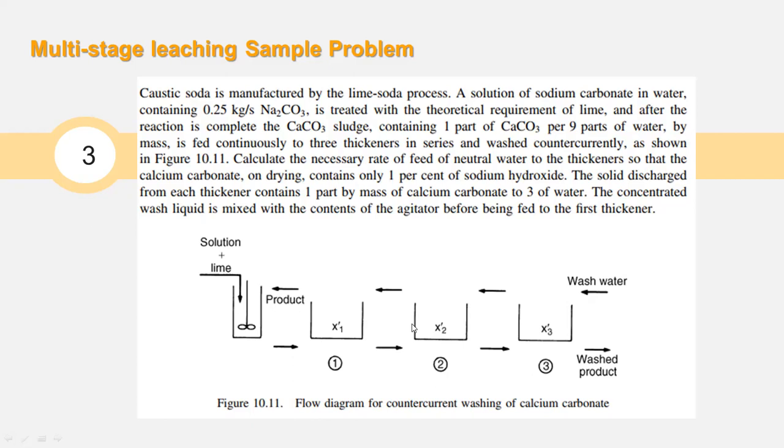The reason why it has the prime in this particular problem is it's not the usual way we express concentration in leaching. If you recall, in the primary principle for leaching, we express concentration in terms of solute over solute plus solvent. In this case, since our X has a prime, it's only solute over solvent, not solute over the sum of the solute and the solvent.